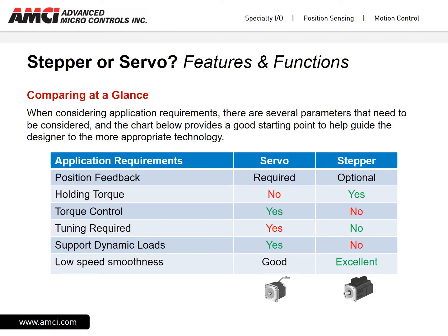Whereas with a servo, to have holding torque at rest, we may need to add a motor brake. Do we need torque control? If we need torque control, the servo would be the logical choice because this is not a feature often found within a stepper control system.